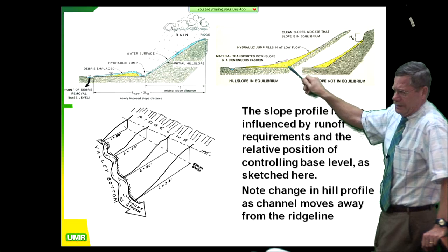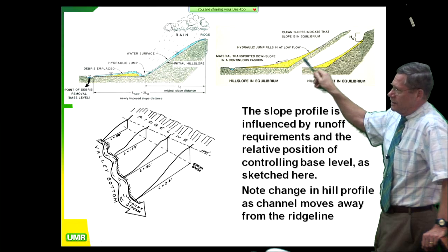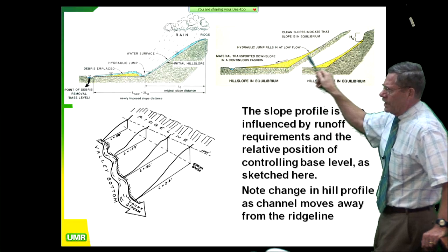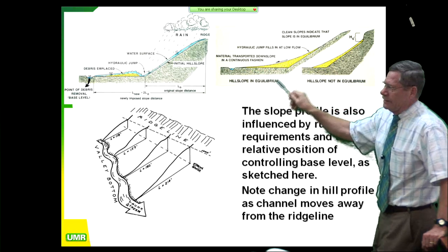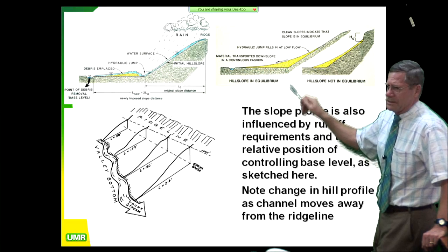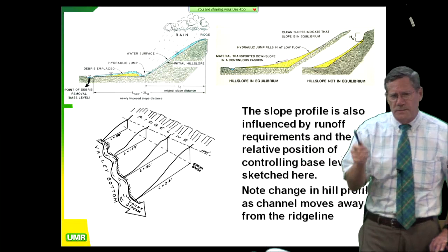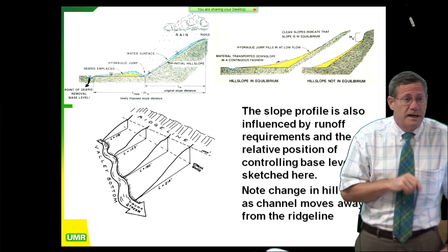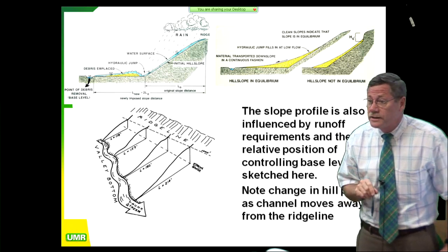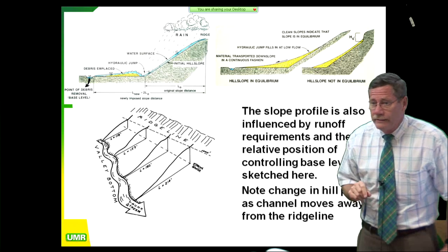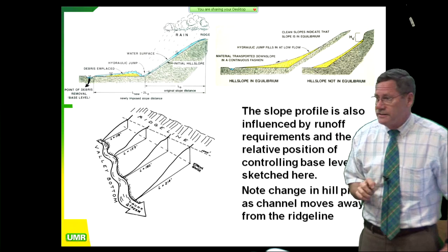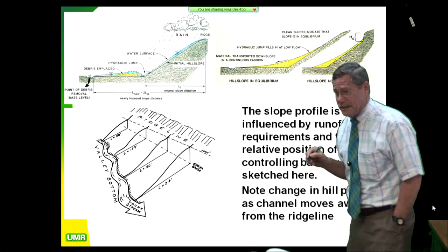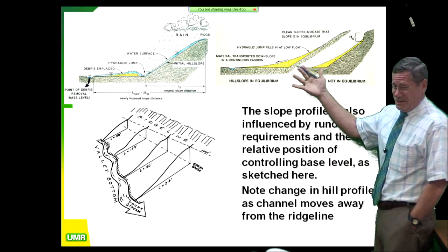Now, if you go back and look at engineering textbooks in the 1890s, they'll show you to construct the embankment like this with a 20-foot radius transition. Never, ever, ever have a sharp transition. That's in the old textbooks from 110 years ago. It's not in any textbook I know of today, because the people writing the textbooks today don't move dirt. They go to faculty meetings and get grants from the National Science Foundation to write computer programs. Okay? They don't even know what the back end of a dozer looks like. So that's not in the books anymore. It's just common sense.